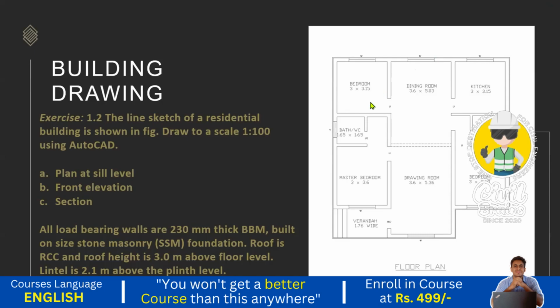So horizontal wall, from here we just start. So what is the distance? Okay, here you can see this one. This distance is different. Okay, this distance is different. These are same. This distance is different, but this wall thickness and this wall thickness is different. Correct? So like that, we need to carefully draw that. So I draw this one first, 3.15. Then I just draw this one next, 5.03 next, and next I draw 3.15, and then here the wall thickness is different, so be careful.